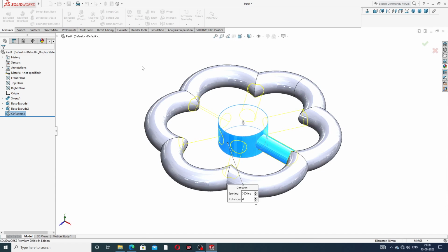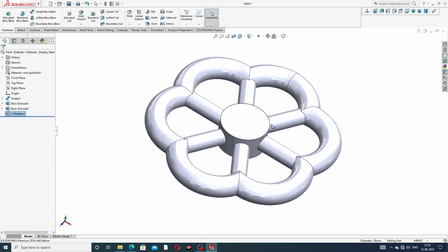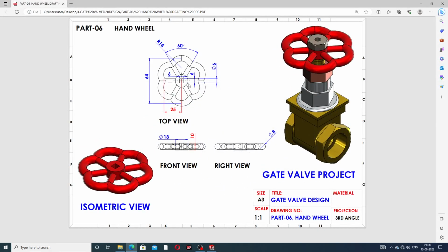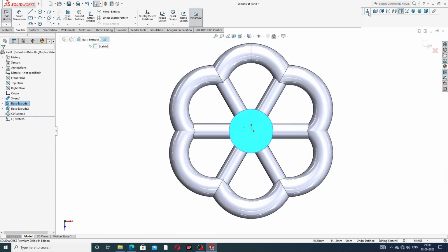Some time is spent here because all is counted here. Okay, this is perfect, and last is drawing this cutout, 6 millimeter thickness, length is 6 millimeter, and width is also 6 millimeter. On this face, sketch normal, and drawing a center line.